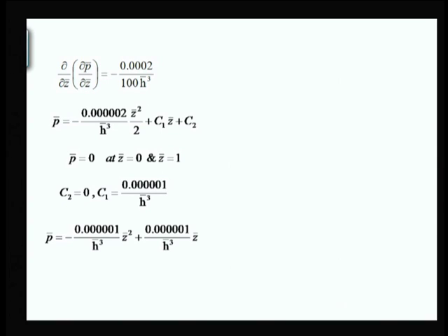So, it gives a two dimensional pressure distribution, may not be 100% correct, but it is going to give us dimensional variation in the two directions, in x direction as well as the z direction, while in the earlier case we found only one profile that was varying only in x direction. We assumed the pressure variation in z direction is not important, and we have not used any pressure boundary condition related to z in that situation.